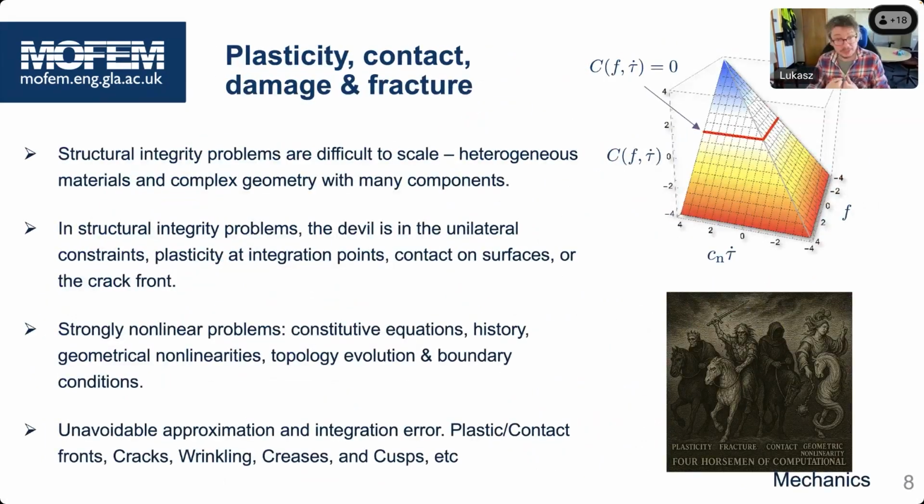But it's not a cohesive element because we are still calculating the release of energy. So we don't have to break the face. We are not using a strength criterion. So we don't have a limit where when the traction reaches a certain value, we break it.